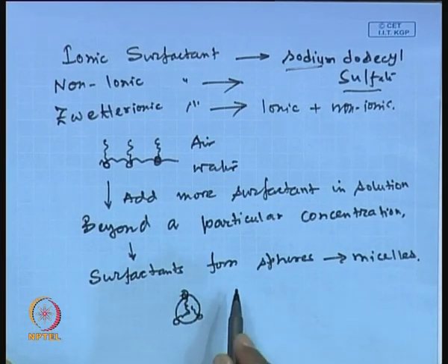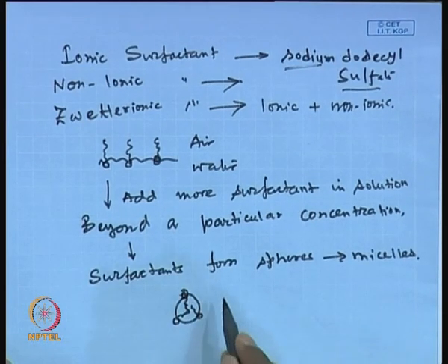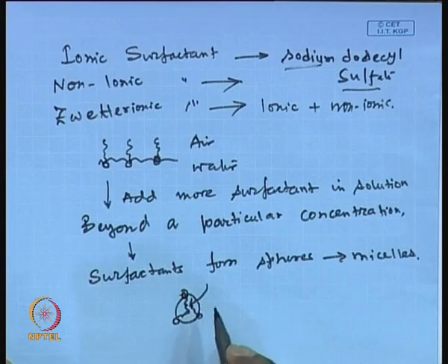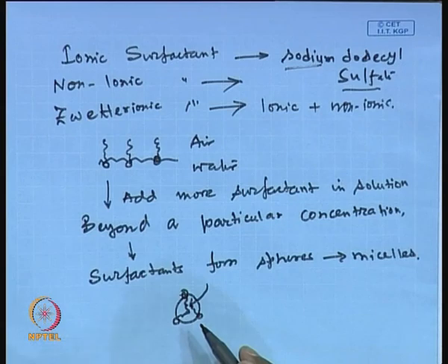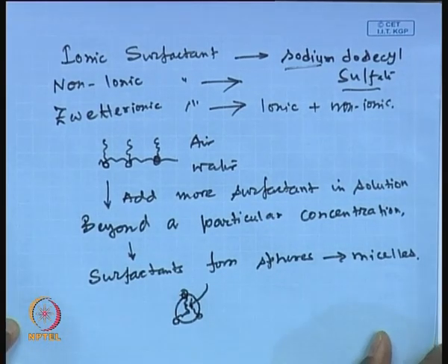So, if a solute that is organic is present, it will immediately go into the hydrophobic environment. It will be immediately solubilized there. Now, these micelles being larger in size, they trap the organics and can be separated by a suitably selected membrane, and one can remove the organic pollutants using micellar enhanced ultrafiltration, and this process is known as MEUF.